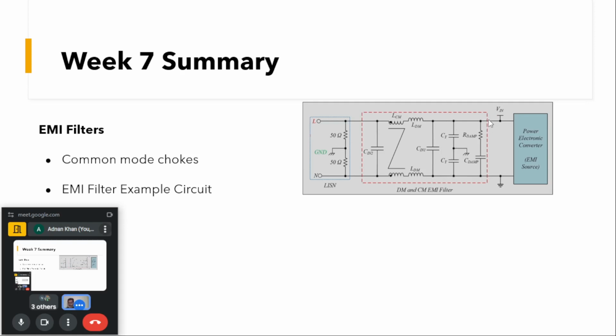There will also be some damping, because the filtering circuit will have some resonance, and if there is not proper damping, then this resonance may persist for some time, and can make our operation unstable, or can hamper the operation of the converter.